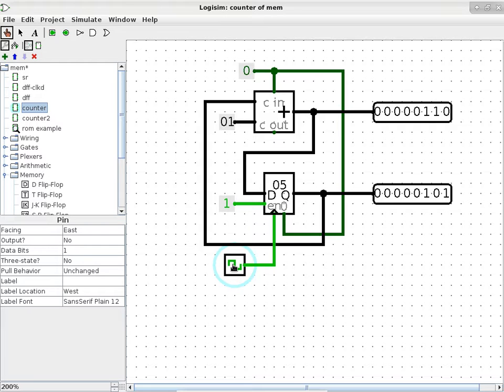So registers are interesting in some other ways too. There's such a thing called a shift register, which is not to be confused with the bit shift operations that we have been doing with all the floating point number discussion. A shift register is interesting because in order to fill in the content of a register, you just need, quote unquote, 2 lines. You need a clock line and you need a data line. Using only 2 lines, you can clock in data into what we call a shift register.